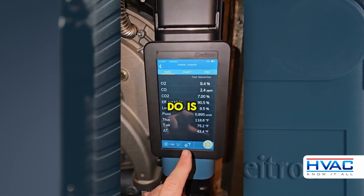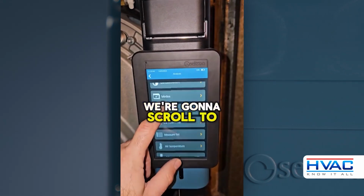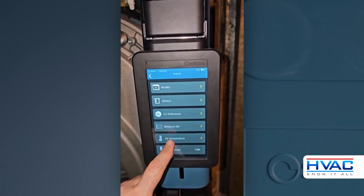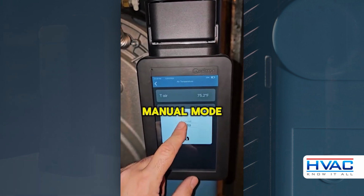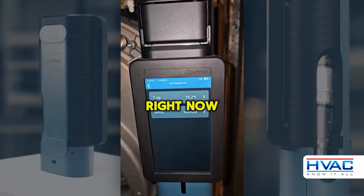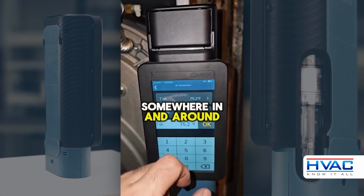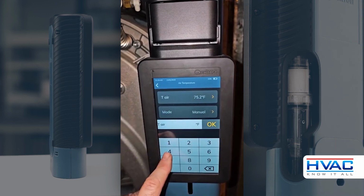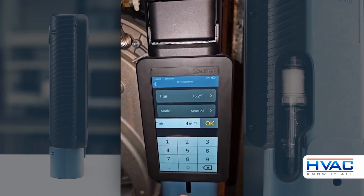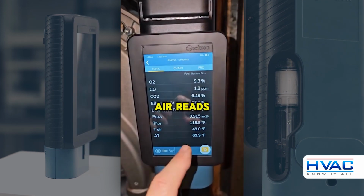So what we're going to do is we're going to go into settings. We're going to scroll to air temperature. We're going to change that to the manual mode. Right now outside it's about 49 degrees Fahrenheit, somewhere in and around there. So what we're going to do is we're going to change that to 49. So now our T air reads 49, okay?